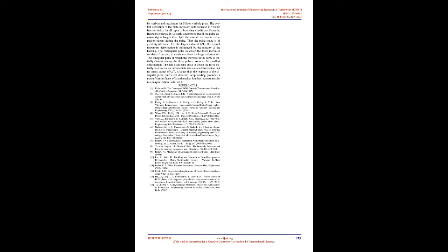A convergence study has been carried out for ensuring the convergence of the numerical results. The results are also extracted from Abaqus CAE by using S8R5 shell elements and are in very good agreement with the developed elements. Free vibration analysis is done to study the different modes as well as frequencies. It is observed that free vibration response is minimum for carbon and maximum for silicon carbide plate. The central deflection of the plate increases with increase in volume fraction index for all types of boundary conditions.